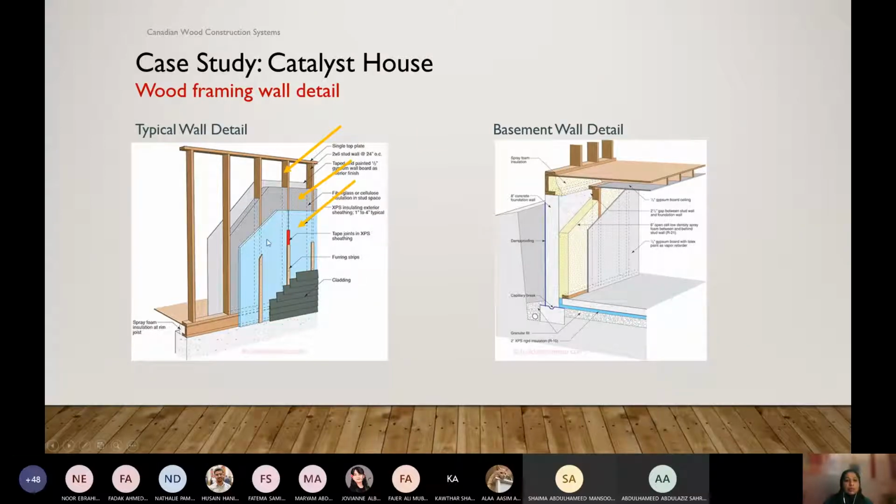And then on top, we have the plywood or OSB sheathing. And then with the help of these wood pieces, we attach our finish material, whatever it is. It could be brick, very thin pieces of brick, or stone, or very common is what we call siding, the horizontal pieces of vinyl or wood for the finish material. And so we attach them.